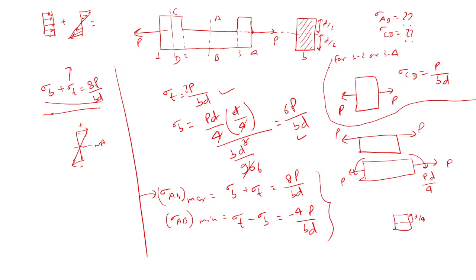And now coming to the mid part, the loading condition is like this, right? Yes, sir. So now we shifted the load to the center. When we shift the load to the center, then a moment will come, because of the shifting of load. So when we shift the load from here to here, how much moment will come? P into this distance. How much is this distance? Because this is D by 2, this is half, so D by 4, P into D by 4. This way the moment will come. And now two stresses will come: due to the bending, stress will come, and due to the direct loading, stress would also be there.